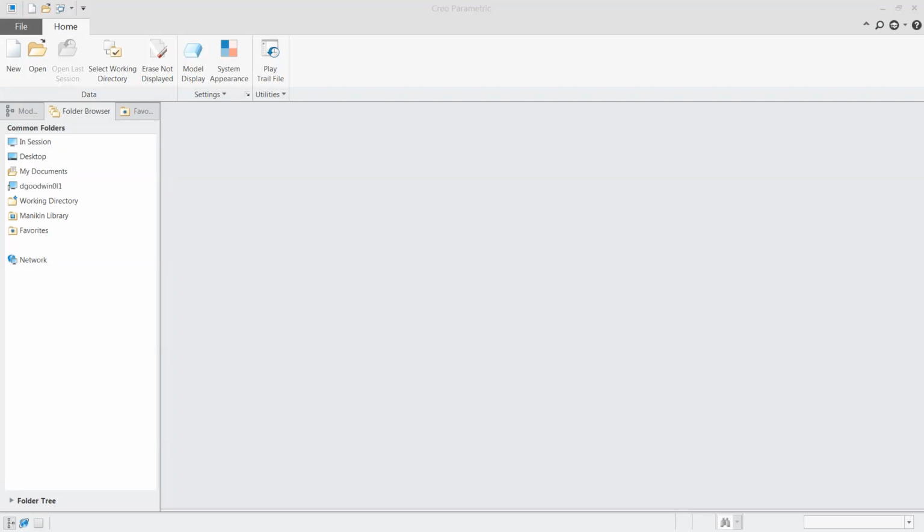So you wouldn't have to have the secondary step of building out a drawing to include all that information, because they're working with the model itself. Now, if you really needed to, you could simply take screenshots of the model in its different states to see the different drawing annotations if you, for whatever reason, weren't able to see the model itself or weren't able to work with the STEP AP242 or the Creo View file. But the idea essentially is that you wouldn't need to work with the drawing file, and that work is pretty much already done while you're dimensioning the model.